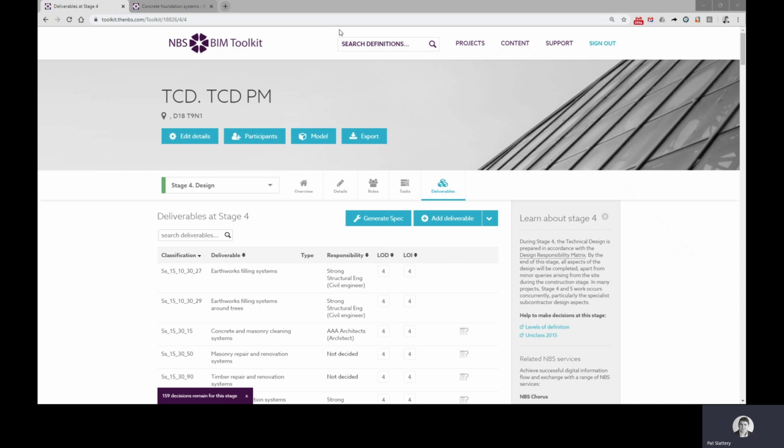It has a particular data structure, and this Excel file, if anyone's been familiar with COBie, they'll have seen this format of an Excel file before with its standard sets of colors. Again, each of the tabs have certain amounts of information. So we have information on the contacts, information on the facility that we put in. We haven't got floors coming from this file or spaces because we've no spaces in the NBS Toolkit, but we do have types. So all of the types of things we put in there and all the components that we have in there exported to this Excel spreadsheet.